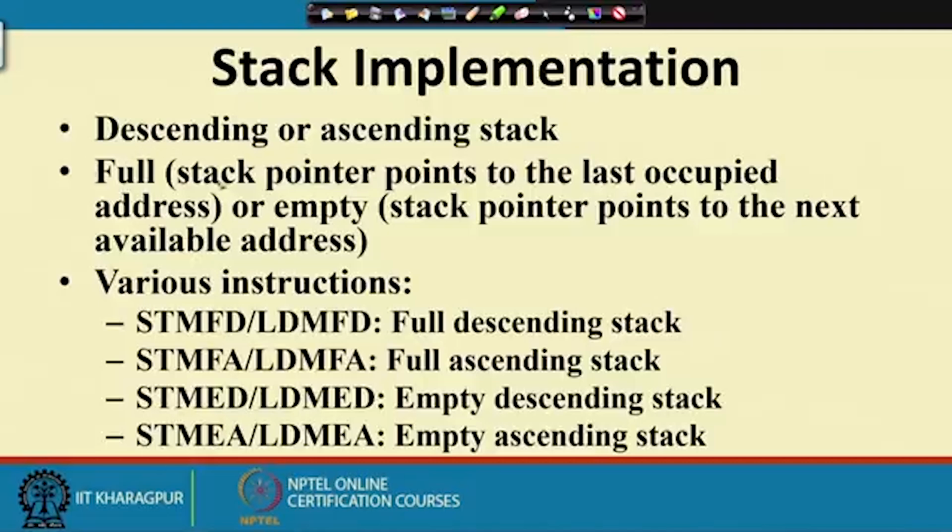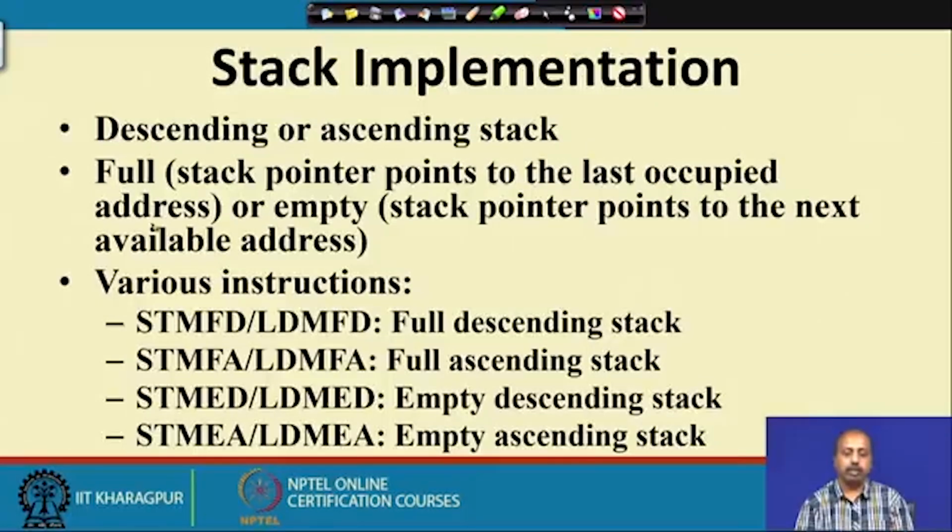Descending or ascending, and full, where the stack pointer points to the last occupied address, or empty, where the stack pointer points to the next available address. We have got different variants of this instruction: STMFD store multiple full descending and LDMFD load multiple full descending. They are used for implementing a full descending stack. Similarly, STMFA and LDMFA for full ascending stack implementation, store multiple full ascending and load multiple full ascending. Then STMED and LDMED for empty descending stack, and STMEA and LDMEA for empty ascending stack.